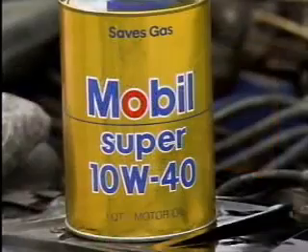In low-temperature applications, lower viscosity oils are usually more suitable. They flow more easily at low temperatures and can reach moving parts better than thicker, high-viscosity oils. In high temperatures, a thicker, high-viscosity oil is usually needed. The oil has to be thick enough, that is, have a high enough viscosity to maintain a film over the moving parts it must protect.